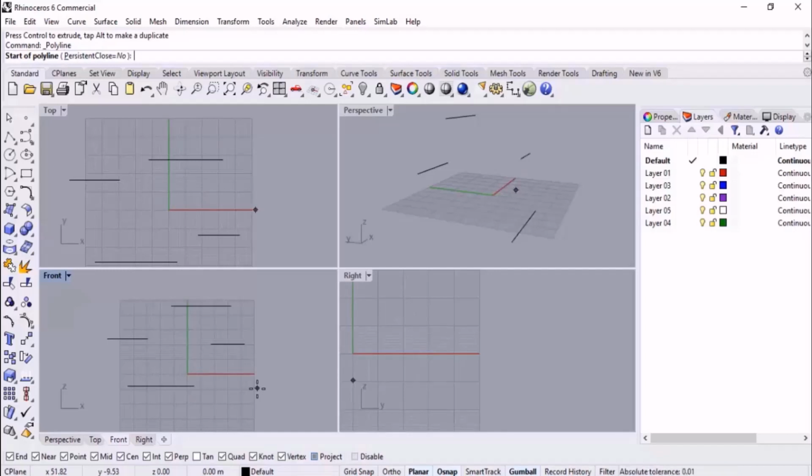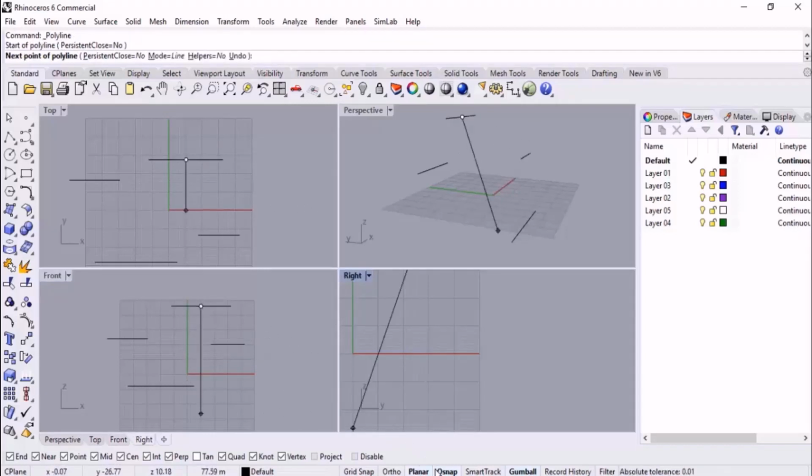So this is the neutralization of the snap: we can't have the midpoints, but the projected midpoints. So in the second that you want to use planar, you should disable project. By this way, then I'm gonna sketch a shape or whatever. Right now, my first or initial point that I specified in the scene is very important. I mean, if I want to sketch something that starts from the midpoint, planar is enabled. And then if I want to connect to another midpoint, if I want to have all of the drawings in the same plane, I should enable project.